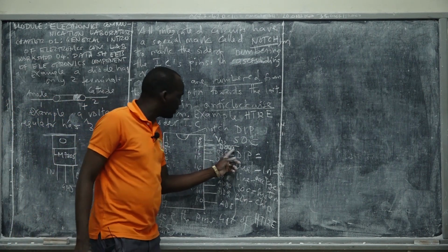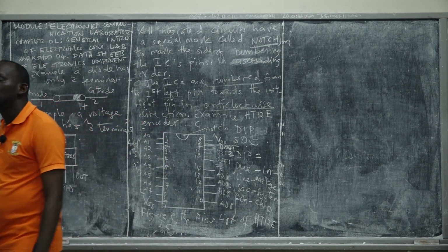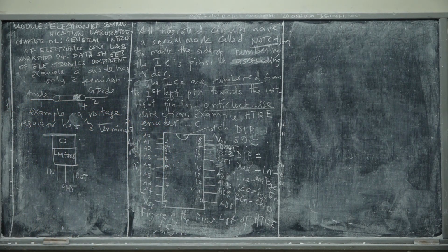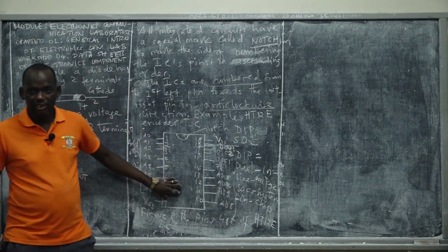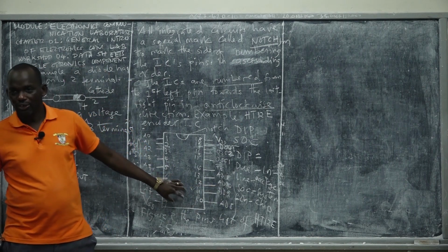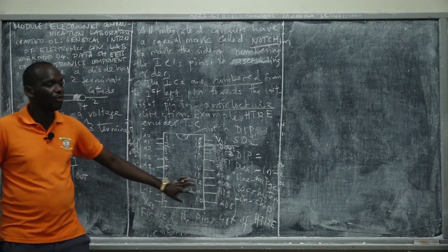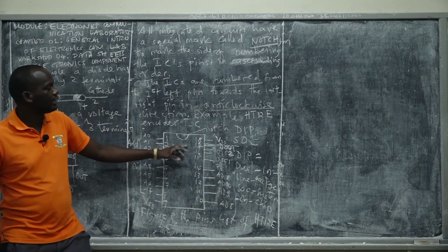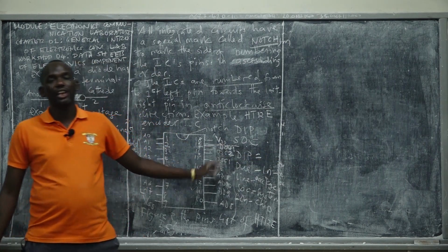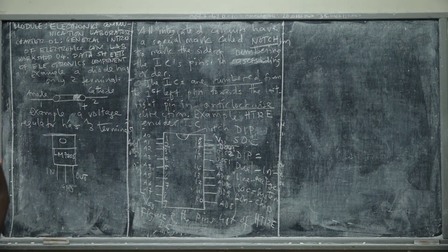Then pin number 17, it's D out. Say D out. D out is what? Abbreviation of data out pin. It's output data pin. It will provide the output from this encoder. You feed the information that may be hello. You just send hello, but in digital form. Then that hello will be encoded, and then you'll get the output which is encoded from the D out or data output pin. All right?